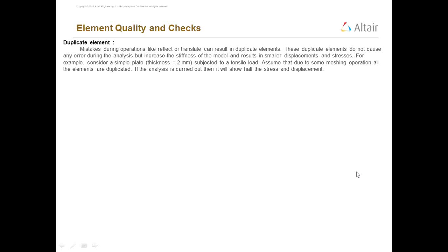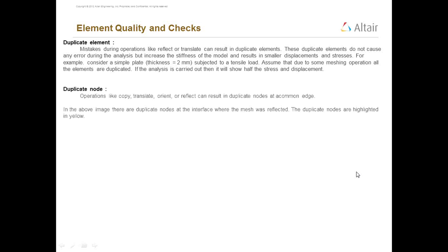Assume that due to some meshing operation, all the elements are duplicate. If the analysis is carried out, then it will show half the stress and displacement.